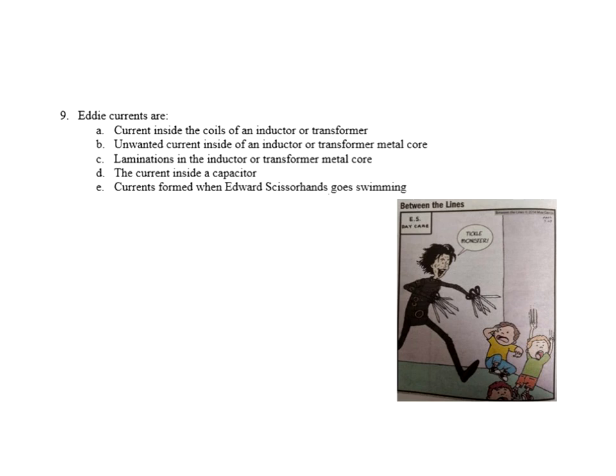Yes. We talked about it in reference to transformers. You don't want current in the metal core. And by the way, the associated question with this is, what can you do to reduce eddy currents? Well, even though this is the correct answer for this question, what we'll see with the associated question is, eddy currents can be reduced in the transformer by laminating the core. Okay, so watch for that one as well. It's one of two variations.